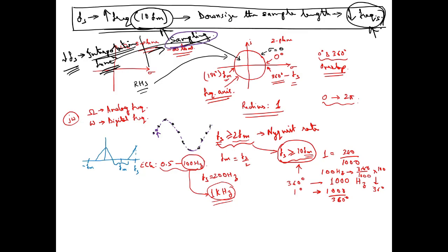At the next stage we can do the sampling after implementing the interpolation function onto the data points, so as to get the envelope of the signal. Once we get that, we have increased the sampling frequency from a lower sampling frequency to a higher sampling frequency, and this is another type of multi-rate DSP.